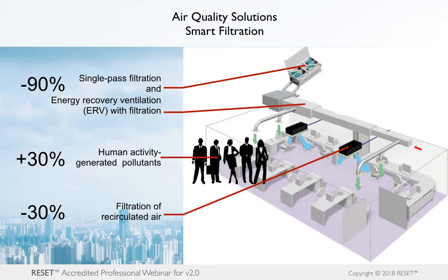Well, it's because of the pollution that's generated by the occupants from walking on carpeted areas, using air fresheners, cleaning products, as well as office equipment like copy machines, and infiltration that's coming from the building itself, like elevator shafts. So again, talking about this idea of understanding what filtration you need on a case-by-case basis, if you don't understand that, and if you're not looking at your overall building in these smaller pinpointed areas, you could be missing the target of where you need to have better filtration.